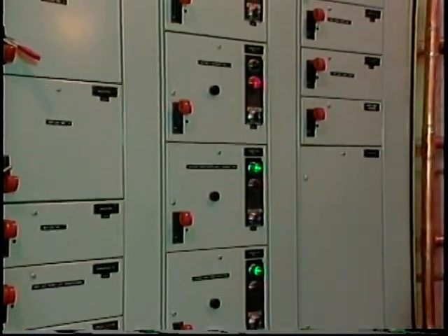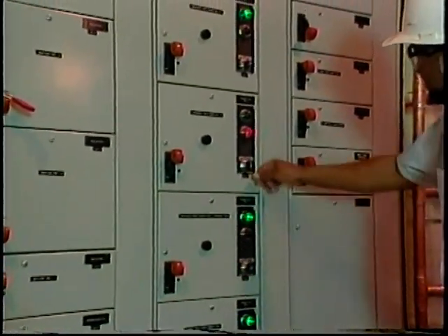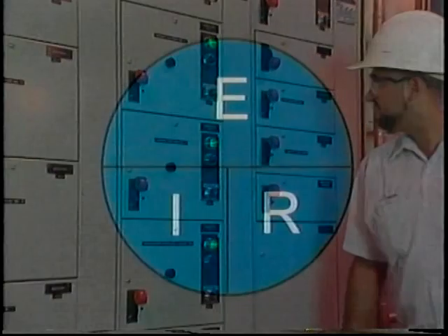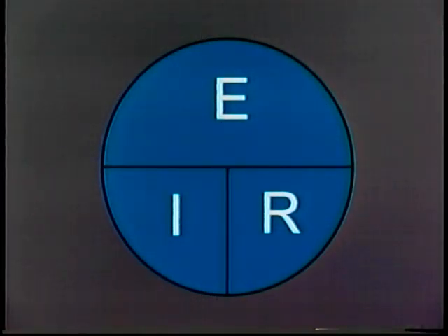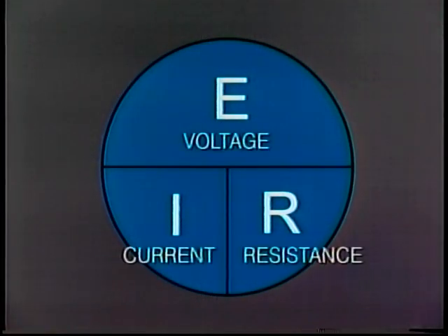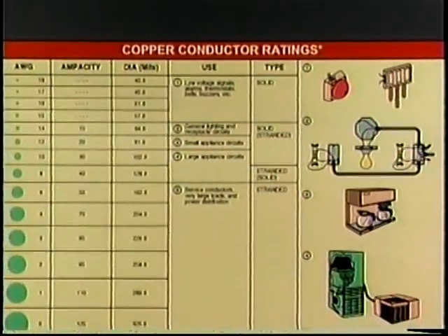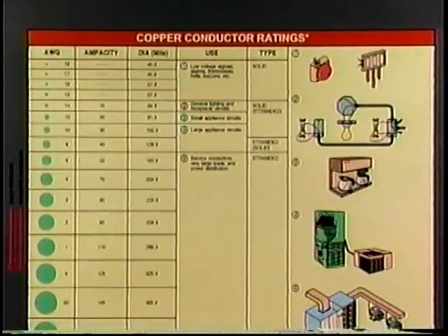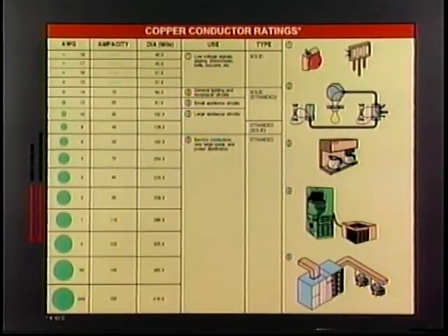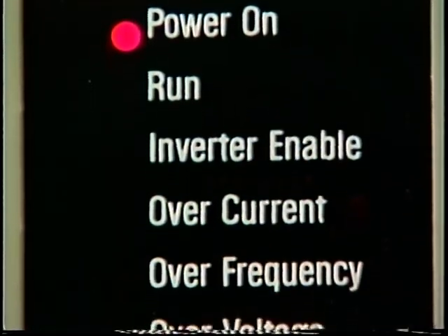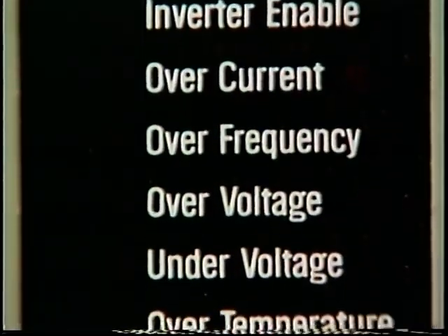Ohm's law is used to predict what will happen in a circuit before power is applied when two of the three electrical values, E, I, or R, voltage, current, or resistance, are known. The predicted value is used to size conductors and equipment, to determine the best voltage level to use, and to prevent potential problems before they occur.